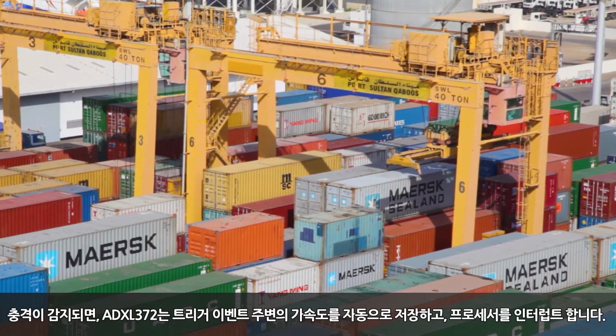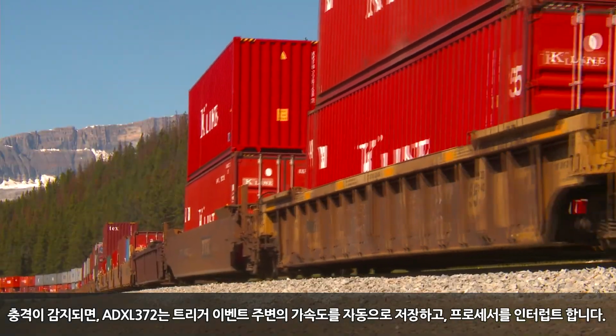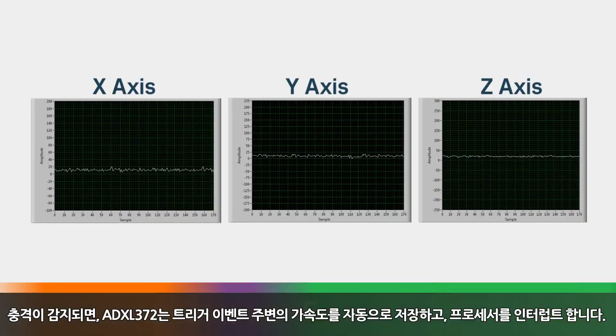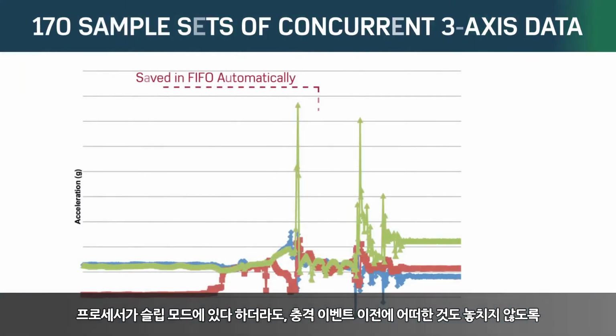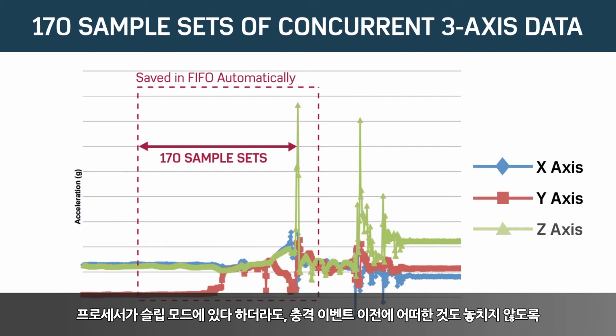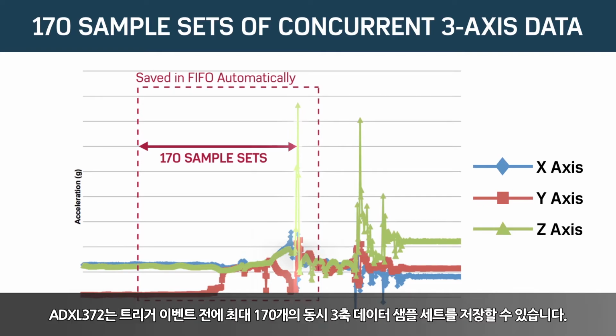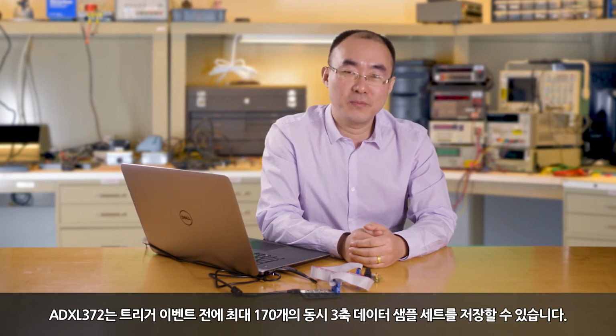Once the impact is detected, the ADXL372 will save the acceleration surrounding the trigger event automatically and give an interrupt to the processor. The ADXL372 can save as many as 170 samples of concurrent 3-axis data before the trigger event, to make sure nothing is missed before the impact event, even when the processor is in sleep mode.